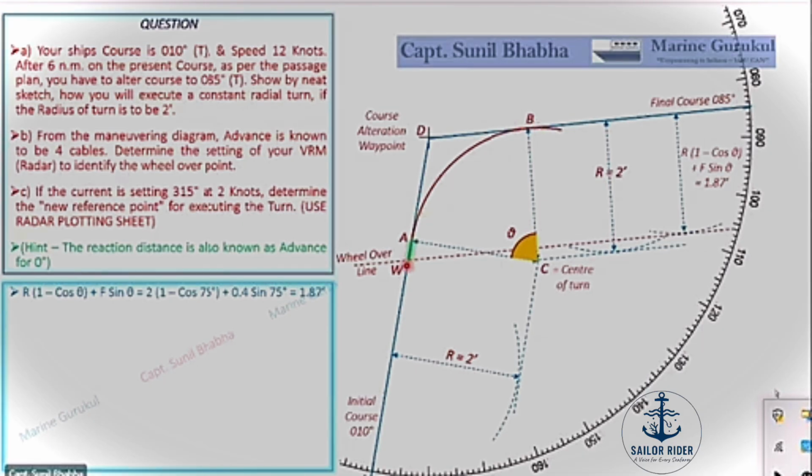That means right from the point W, whiskey point, how much time is the ship going to take to reach up to point Bravo? You see this particular segment of the track, whiskey to Bravo. We will be giving a helm order, the vessel will be moving on a curved path. And during this curved path, it is not possible to counteract the current using the chart work techniques.